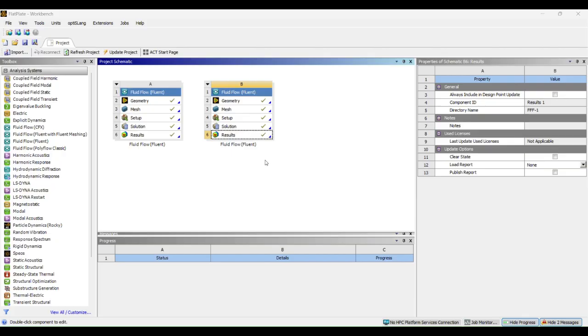Basically, I'm dealing with the analysis of the results of a meter-long flat plate with a 2 meter per second wind gust going over it, analyzing the velocity profiles, the boundary layer thickness, shear stress, skin friction coefficient, and drag coefficient.